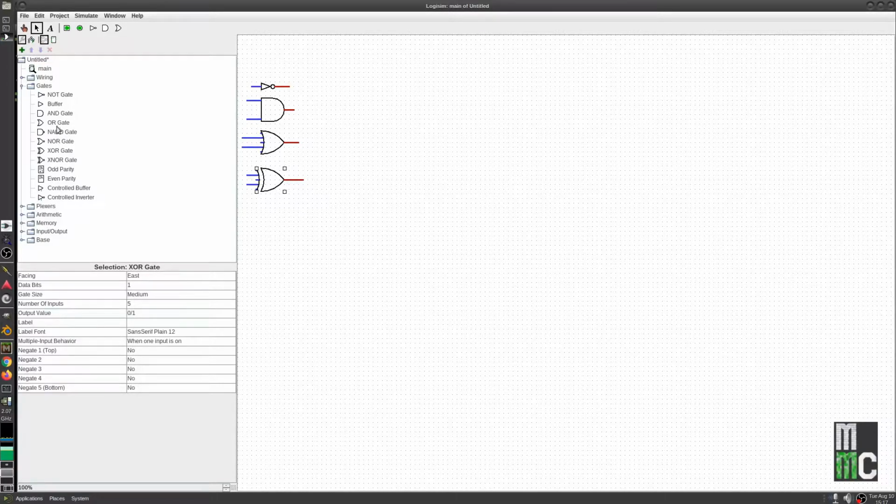The last one we have talked about, I'm going to put it right here by the AND gate so you can see. This little circle on any circuit, this little black circle you see in the one here, indicates that a signal is negated or inverted. That's why this is a NOT gate. That means the difference between an AND gate and a NAND gate is your output is going to be inverted.